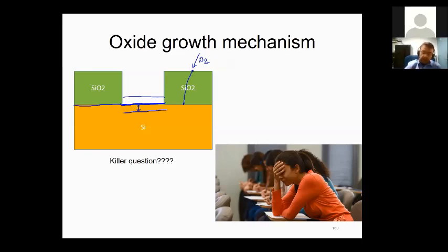So that makes this process on the sidewalls slower than the process here, because here it just sees the bare silicon and it can grow the oxide much quicker. So this is quick. What I'm trying to say is the total thickness that I will grow will be thicker here compared to the total thickness on the other portions. So I will not be able to eat away that much of silicon here. So it's going to be higher. You see, the levels are not going to be the same. So it's going to be a little higher.